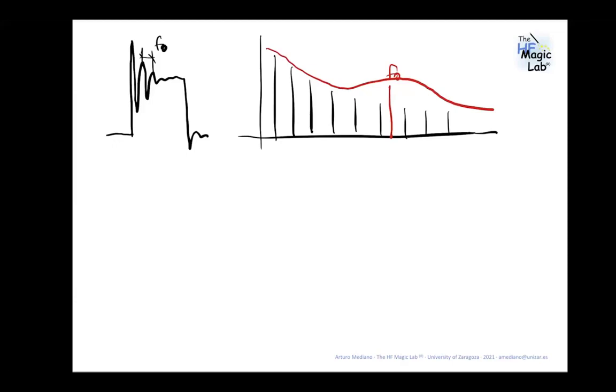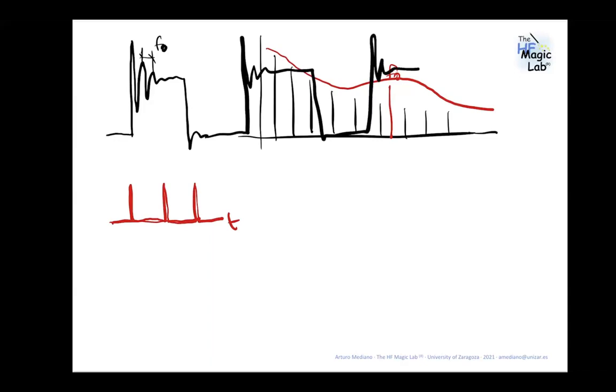What you need to consider is what happens if you see a signal that in time domain is doing something like this. This is time domain, no? It's a peak. It is repetitive, no? So what you need to think is the signal is repetitive. Constantly, you have this peak here, no? So it's like you have two signals. One is the square wave signal. The other is the underdamped ringing. But the underdamped ringing is periodic, okay?